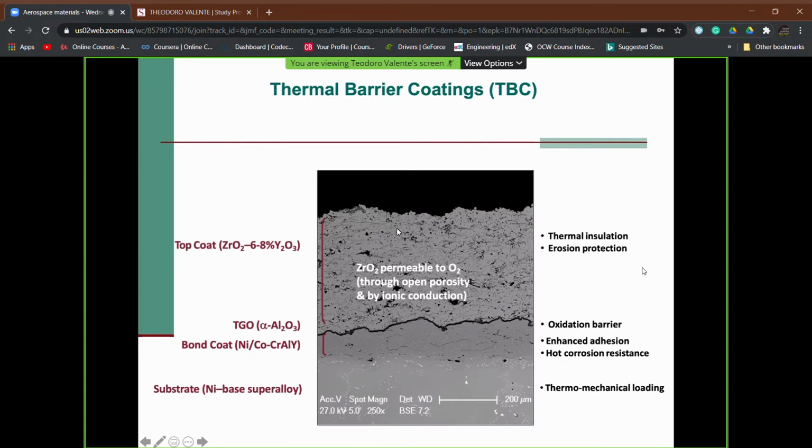But if we see this micrograph of the zirconia, you see a quite relevant number of dots, or black points. These black points are voids. That means this coating, according to the currently most performing fabrication technology, which is plasma spray, is fabricated with a residual porosity which is around 8 to 10%.